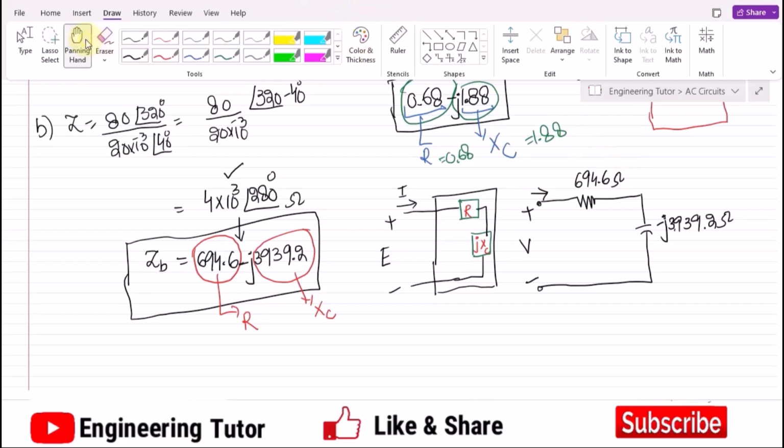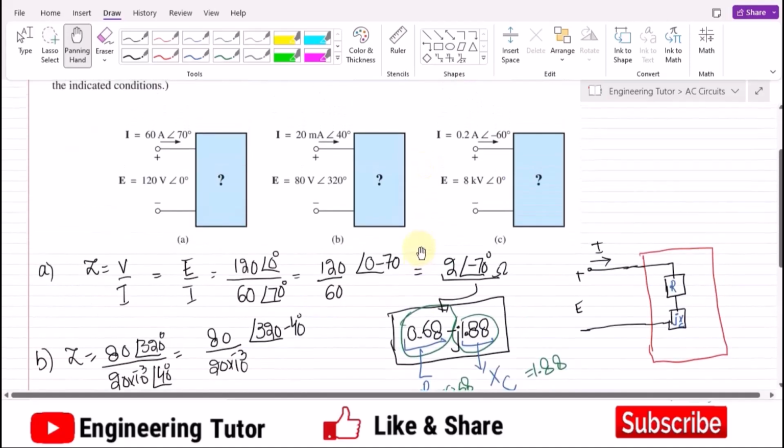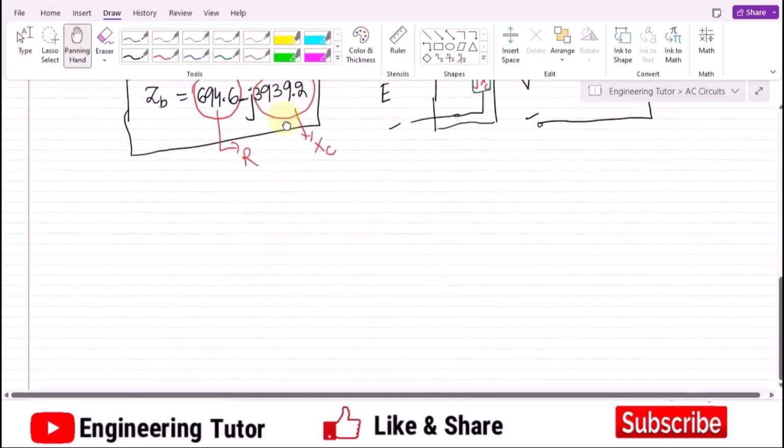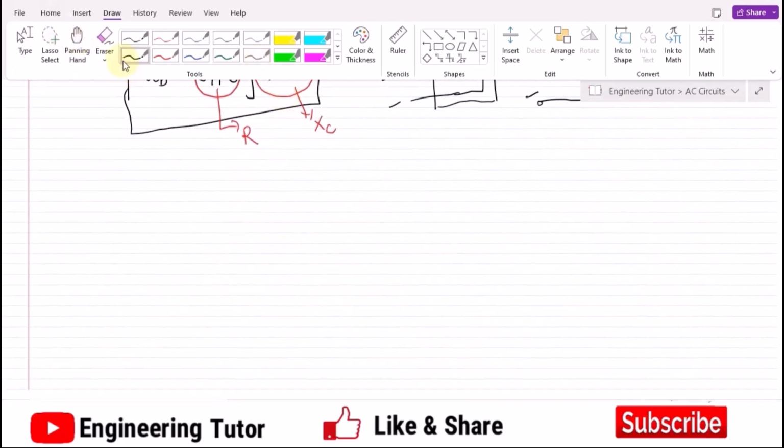In part 3 of this question, again let me come towards it, and again find the value of the impedance which is inside of this black box. Okay, what we have to do, again we have to use the same formula, and for that E is 8 kilovolts with the 0 degrees phase, while the current here is 0.2 amps with the minus 60 degree angle. So here let me start part C.